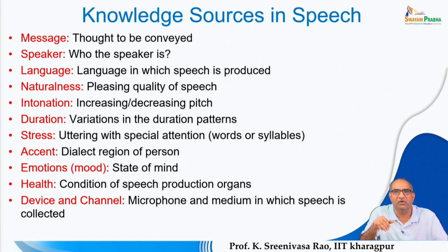From a waveform point of view, you can see the pitch in terms of a periodic pattern. That means in a waveform the same signal pattern repeats successively, so you can say that the signal is periodic. Pitch is the number of times the periodic pattern repeats in a second, and the pitch period is the inverse of that. The time required for one period of the signal is known as the pitch period. So the reciprocal of the pitch period is the pitch, because the number of periodic patterns per second is viewed as the pitch.